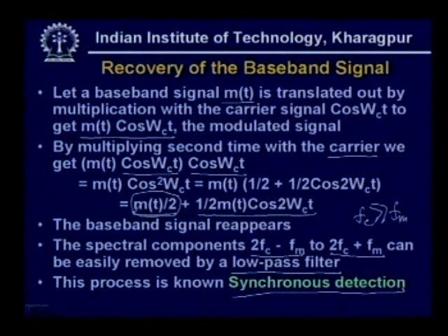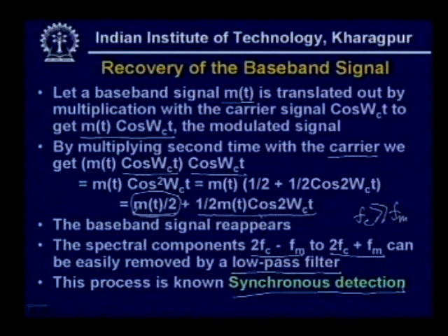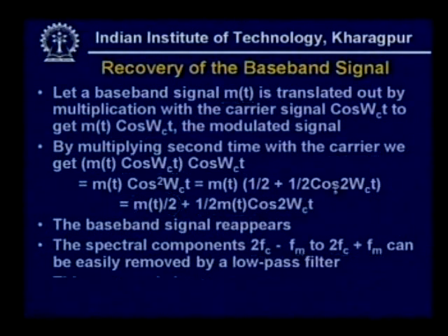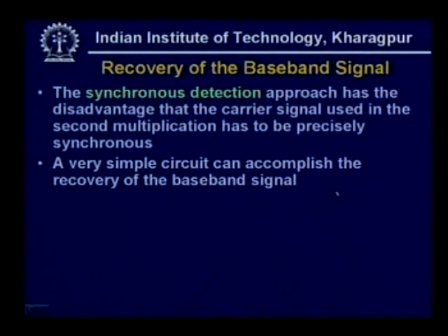Now, there is one important limitation of this synchronous detection. The important limitation is the signal cos 2πfct has to be precisely synchronous.